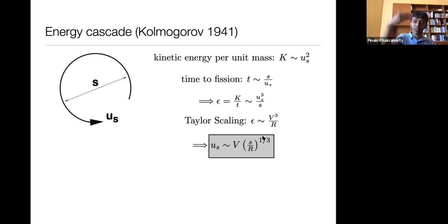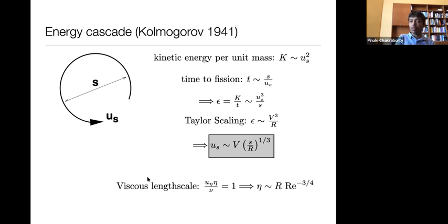But the same analysis also tells us where this cascade is going to stop, down at the smallest scales. To get to that, we can simply argue that at the small scales, which sometimes are called the viscous length scale or the Kolmogorov scale, and I'm going to denote it by eta, we can compute what the local Reynolds number is. And Reynolds number is, of course, a ratio of inertia to viscous effects. If inertial effects and viscous effects become comparable, we can take that local Reynolds number to be equal to 1, substitute instead of U_eta this expression over here, simplify the algebra, and we arrive at a power law that tells us how the smallest length scale, the Kolmogorov scale eta, becomes progressively smaller and smaller as Reynolds number increases. There's another power law where eta goes as Reynolds number to the power minus 3/4.